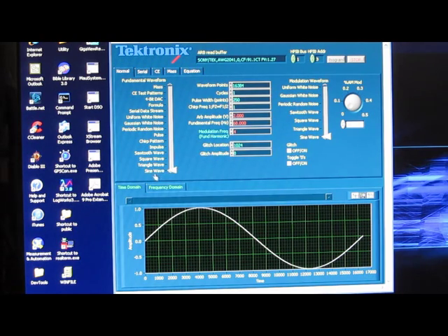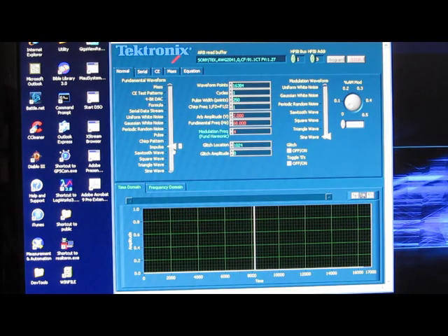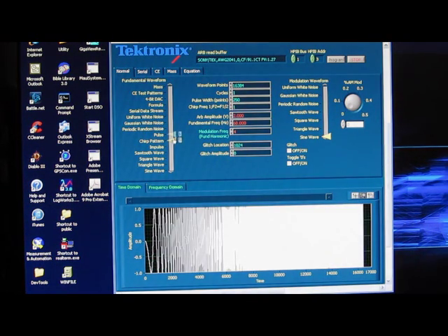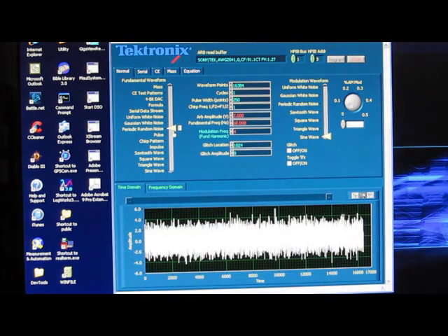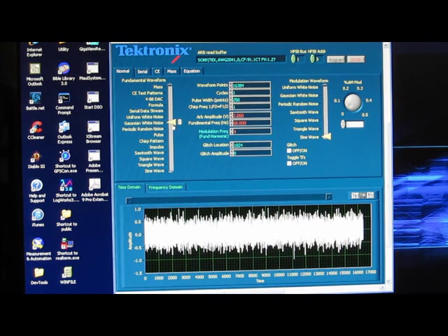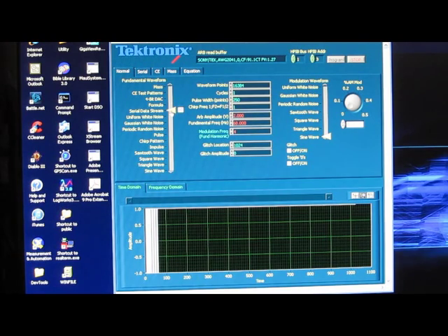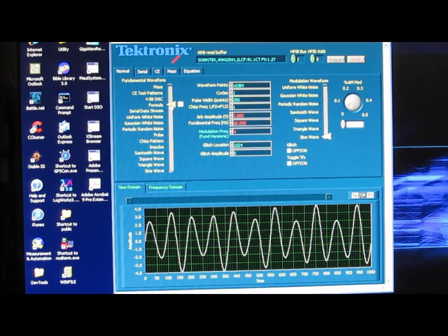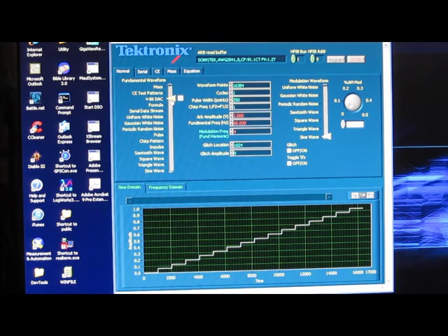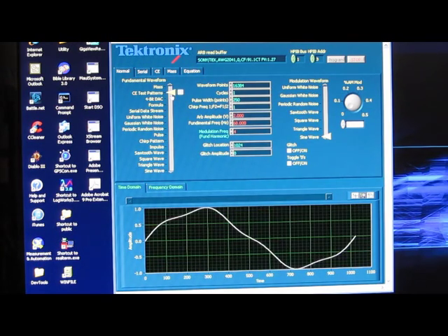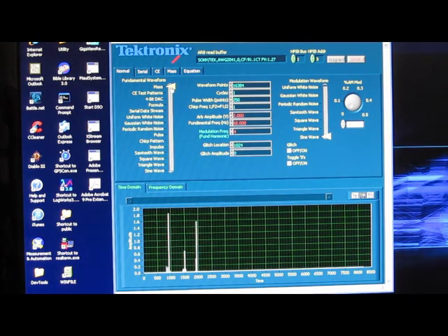There's some pre-canned ones. So you have a sine, triangle, square wave, sawtooth, impulse, a chirp, pulse, periodic random, Gaussian white noise, uniform white noise, our serial data, a formula that you can just enter in whatever formula you want, a 4-bit DAC, some CE waveforms. This would be for a European standard, and a mass spectrometer type simulation.